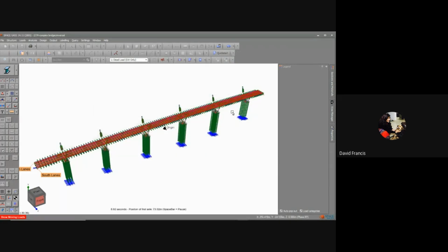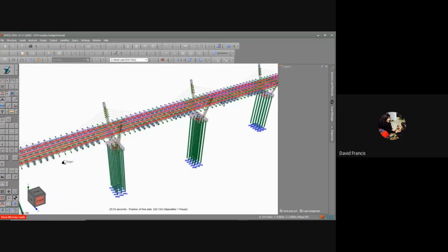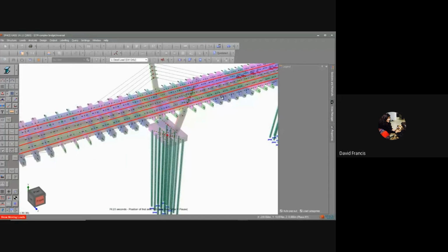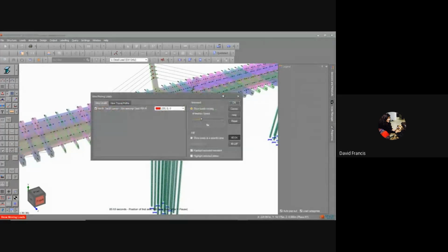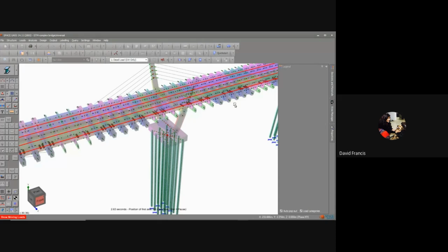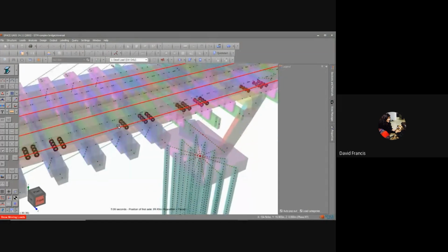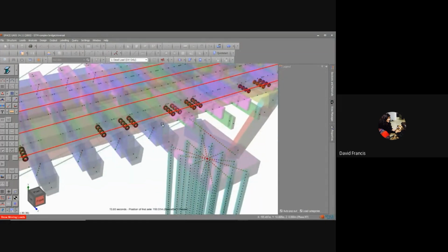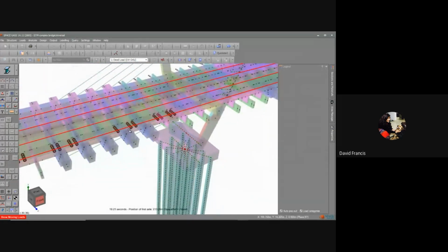Let's view the loads moving. And you'll see that I've got groups of vehicles going down two lanes on each side, and of course this is generating the primary load cases, and also allowing you to combine them with other load cases as well. So it will generate both the primary and the combined load cases in one tool. If I make that a bit slower, we can have a quicker look, and you can see the wheels are there. So we have both wheels and tracks, and of course that's moving in different directions.